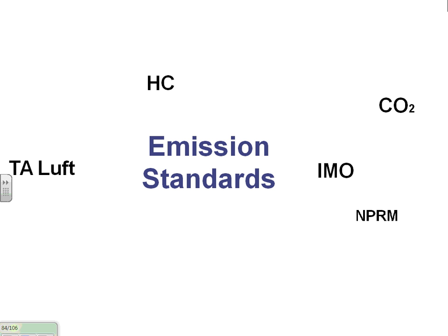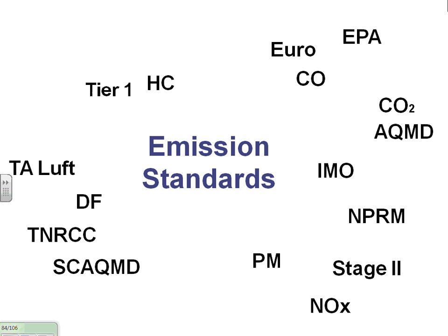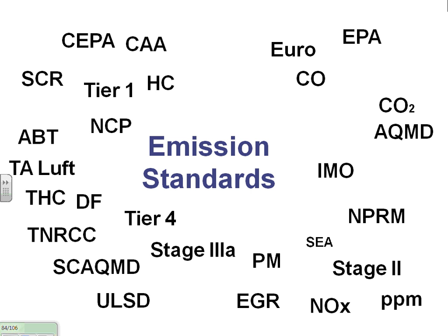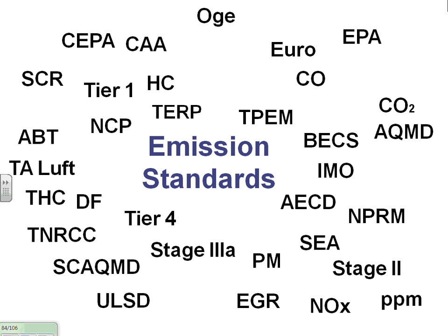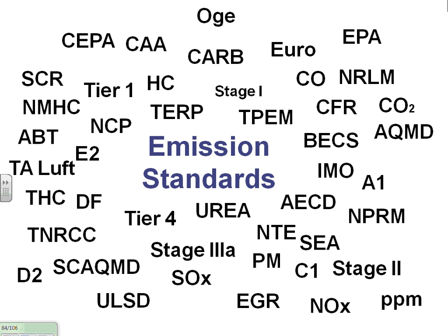All right. Other considerations that you need. This one has made me very old, and I'm getting older. Emission standards. They continue to grow. We're dealing with emissions escalating now for generator sets as well. As you get into generator sets, you're going to find that some of the costs you were concerned about, what's the most economical earlier, some of these costs are going to go totally nuts. We're going to double, triple the costs of generator sets to address this issue.